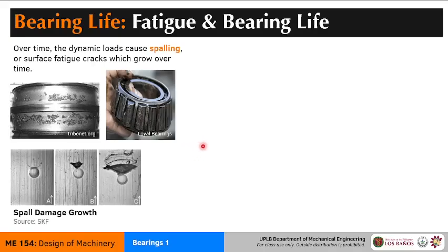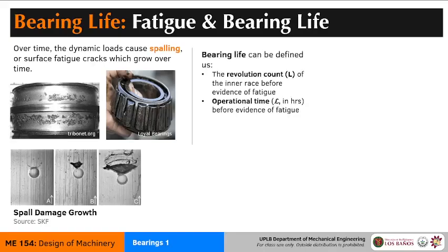Even though in the past we may have used strength to determine where the bearings have to be replaced, nowadays it's more acceptable to just count the life cycle of the bearing and then work our way around that in order to determine what kind of bearing we should buy from our manufacturer. So instead of strength, we look at the lifespan of the bearing.